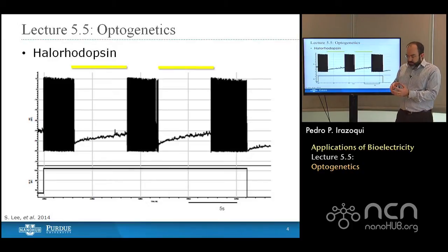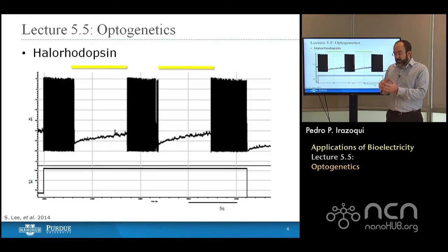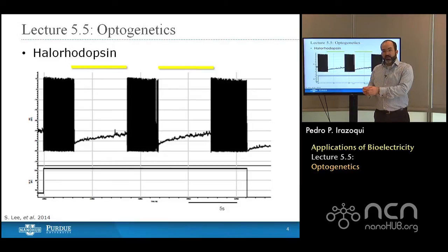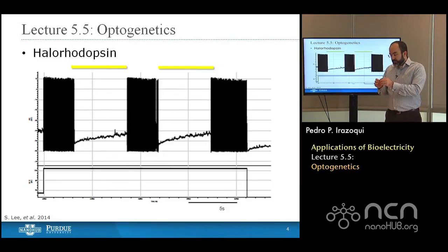When biologists say they want a high impedance electrode, they don't actually mean that they want a high impedance electrode. What they mean is they want an electrode with a very small surface area so that they can either stimulate a small volume of cells or they can record from a very small volume of cells. Ideally, what they would like to have is a very small electrode with also a very low impedance, because a high impedance only gives you noise. So really what you want is a small electrode area rather than a high electrode impedance. But when we're looking at that, there are limits to how far we can go.